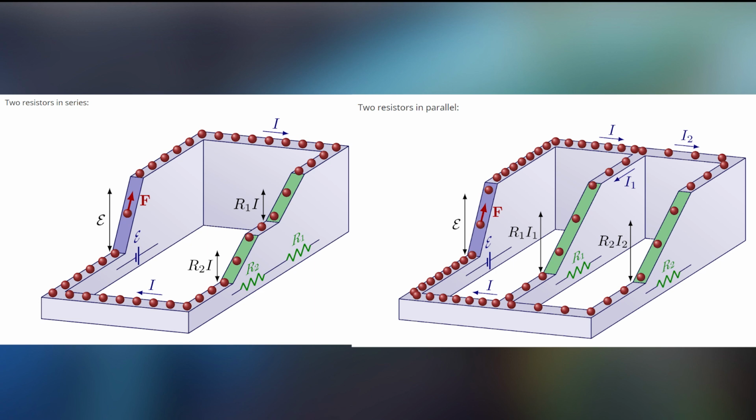And also, each outlet is usually wired up in series with a fuse or circuit breaker, which is a device designed to break, and therefore break the circuit if the amount of current flowing through that portion of the circuit exceeds a certain amount. The way it works is effectively it's just a thin wire or something like that, which will blow out, which will literally be destroyed, like a light bulb that eventually breaks. The wire is destroyed when more than a certain amount of current flows through the wire because it overheats.